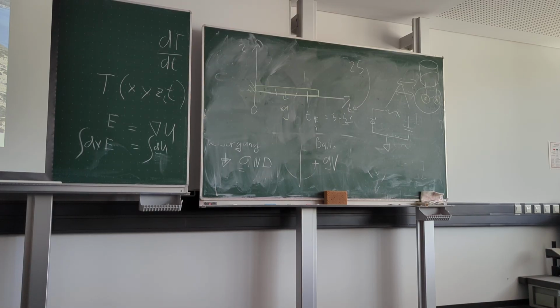So we have to select the region which contributes to the body load. So it's obviously the bar or the beam, number 3. And then we go down. The load type, force per reference volume, is okay. And we'd like to apply a force in z direction, which pulls in the negative z direction, so it has to be a minus force.